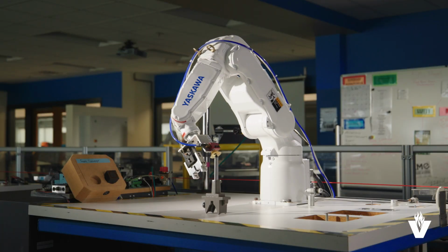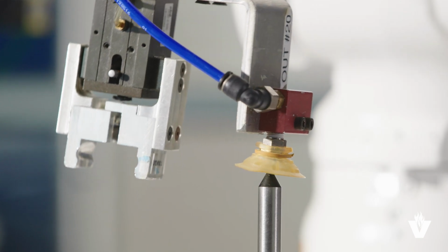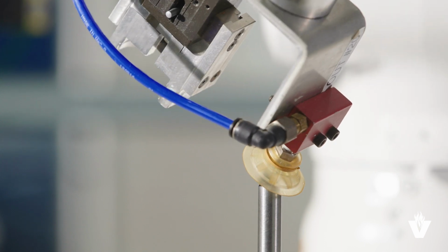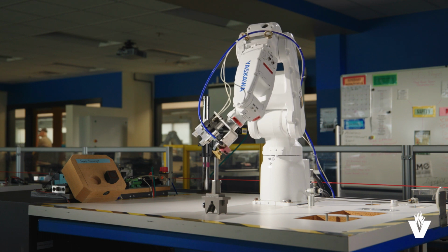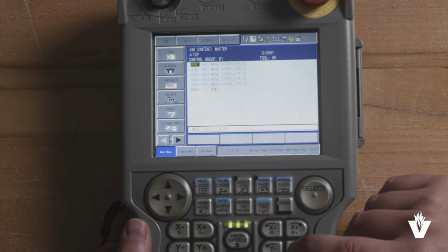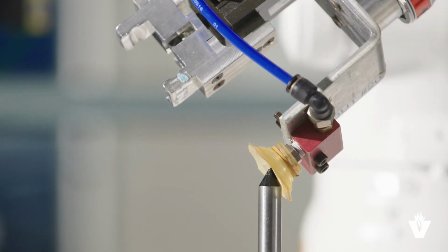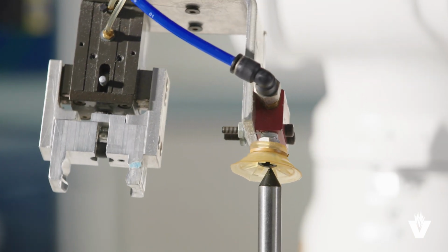After selecting the tool file, the programmer should test the active TCP to verify the proper setup with the robot and the tool coordinate system and the appropriate tool file selected. Manually move the robot's minor axes around the fixed point in space. The center of the tool should not drastically deviate from this point.